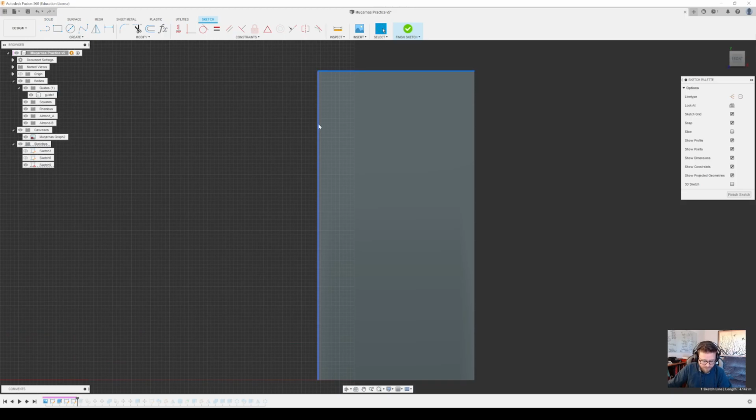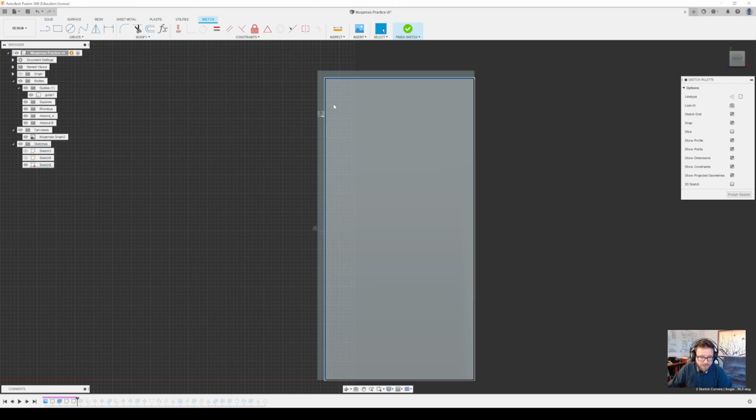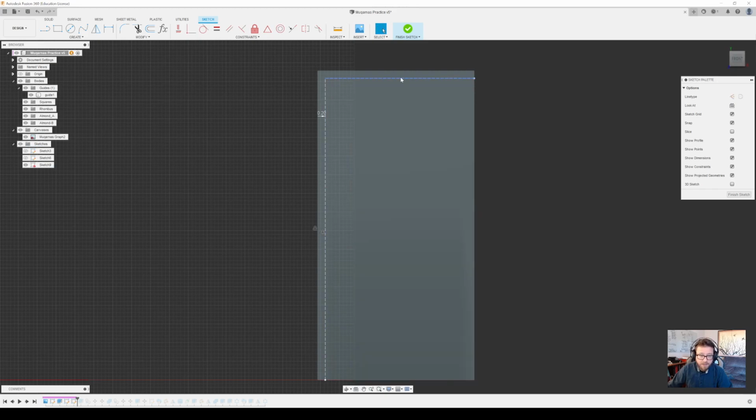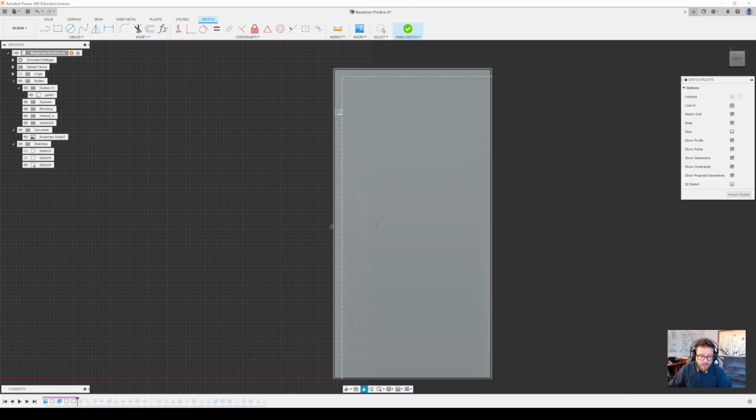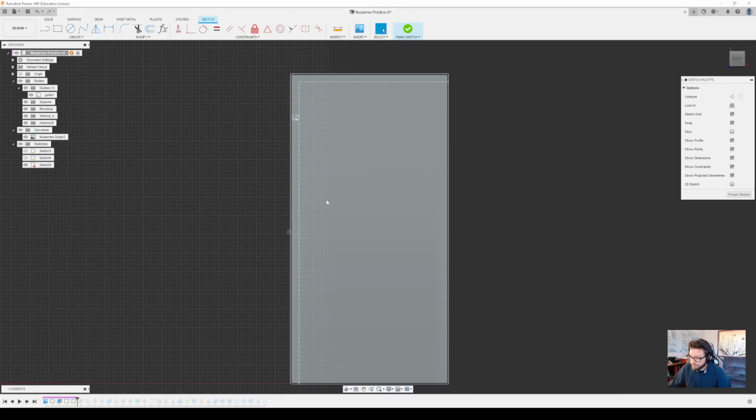What I want to do is just select these two, and I'm going to offset them just to bring it in, and I'm going to say -0.2 because we still need a frame for everything, so that's why I'm doing that. I'm going to select both of these new lines I created and hit the X key to turn them into what are called construction lines, so that they don't get in the way temporarily. I will be drawing right over top of them a little later.